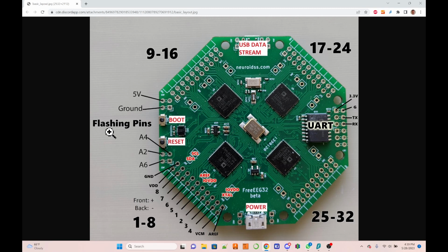So you connect both the machine and the person physically with a copper wire to the ground pin on the wall outlet. This is a battery-operated system, which has many advantages. But that being the case, we do not want to ground the actual device, because it's a battery-operated system.